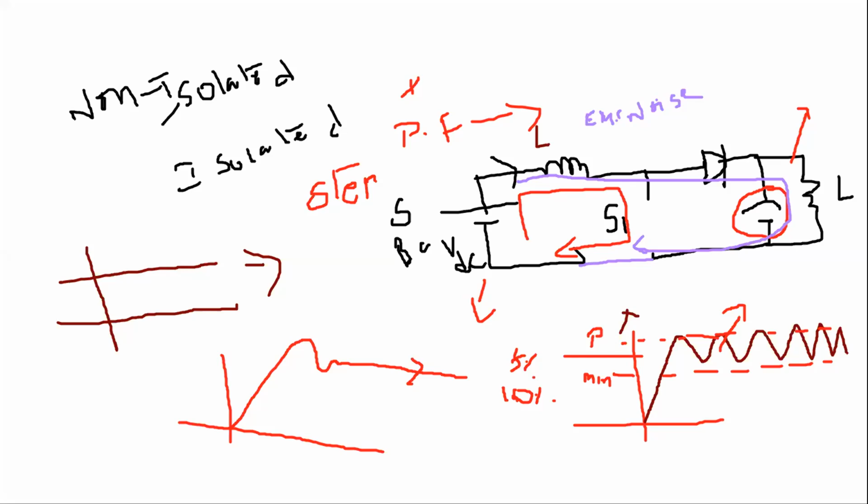Look at here. So this one, whether it is non-isolated or isolated, you tell me. Whether it is a step up converter or step down or a combination of both, you will study it in our academic year. Whether this boost converter or step up converter is non-isolated or isolated. It is non-isolated, right? Whenever we are sending the supply by using a DC link path, we can call it non-isolated.